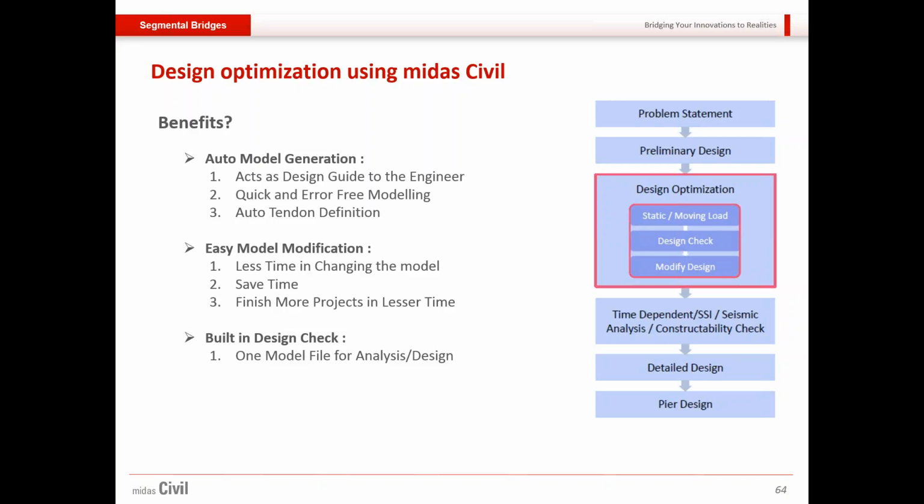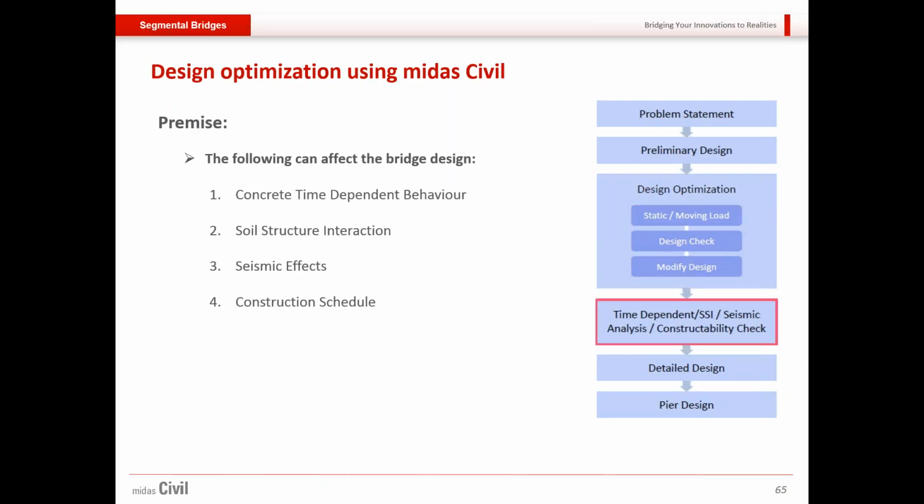And it has built-in design checks. All of this is done in the same file. Okay. Besides this, the time dependent behavior could also be added. Soil structure interaction. So what we did was we just made the deck and the piers, but manually you could add the pier caps below this, the pile cap below it, and the piles could be added. These piles could be given their own springs and the analysis could be performed.